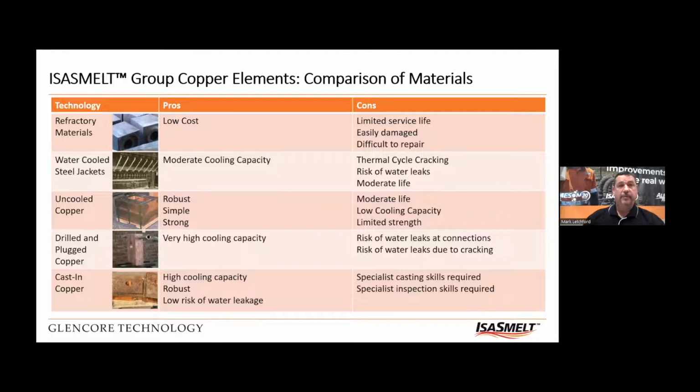And then the brickwork is subject to thermal stress, thermal shock, erosion, and mechanical stresses from barring, or mechanical damage from barring or oxylancing, or even perhaps tapping machines. So they're pretty subject to failure, and they're very difficult to fix when they go wrong. That can definitely have a big effect on the output of your furnace and its productivity.